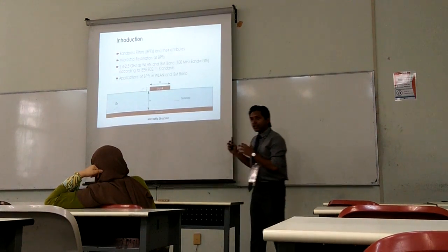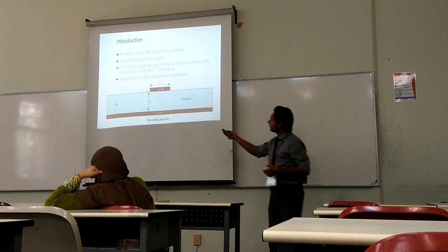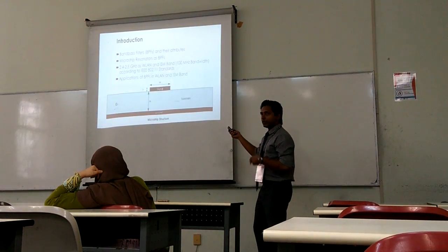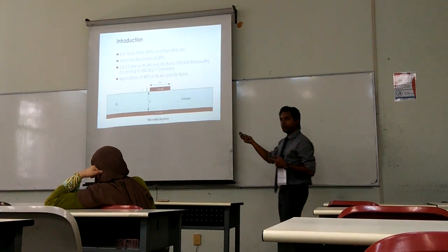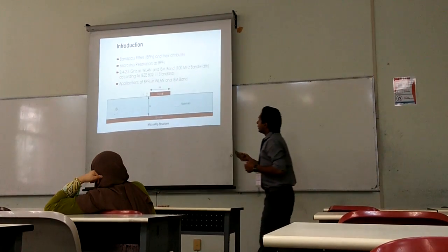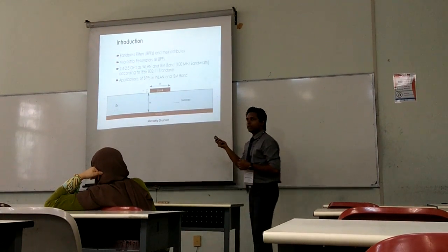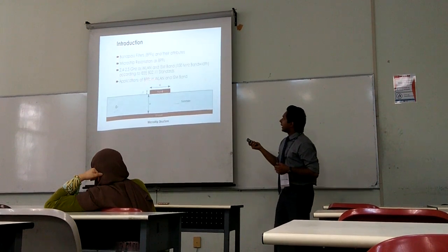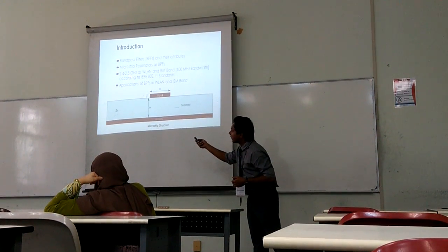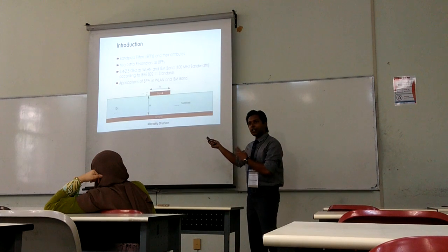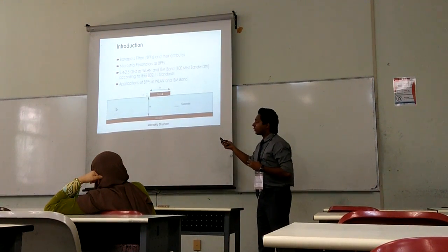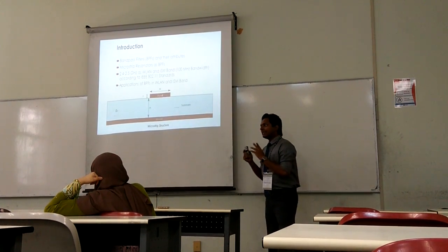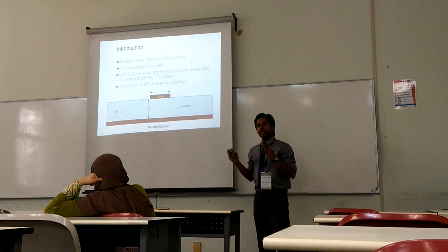So by the way, for our design, we have chosen this 2.4 to 2.5 GHz as WLAN application and ISM band application, the first band, according to the IEEE 802.11 standard. And for this band, there are a lot of filters we have explored, and there are a lot of applications for this. Especially this band, as we see, it's 2.4 to 2.5, so it's 100 megahertz. There are 9 channels according to this standard. So this 100 megahertz is very important to sharply select. If you select from the left side, our band signal, there may be some interference.